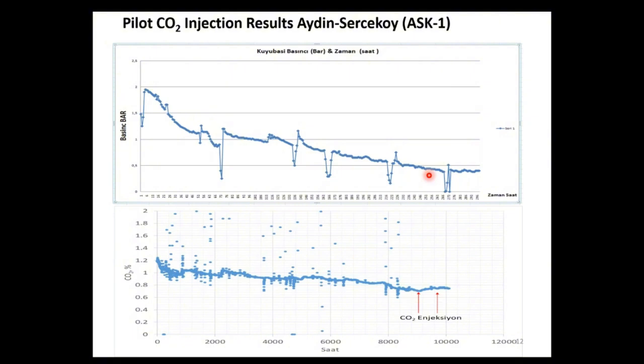in place, plus the CO2 with the brine makes a certain acidic condition, plus the formation is mainly carbon dioxide. When you have a certain carbonic acid, a very weak carbonic acid, for a certain time, slowly it makes an improvement in near wellbore permeability.